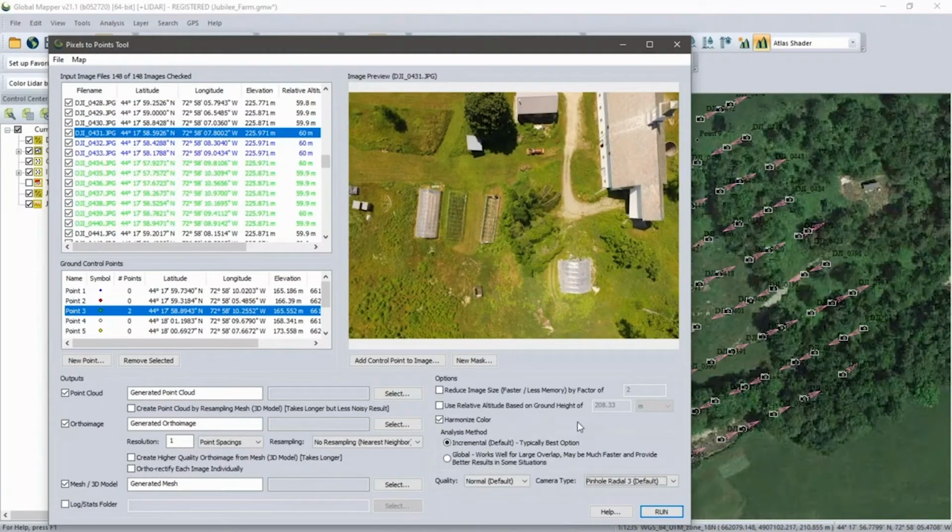Someone was asking about the coordinates, specifically where the coordinates are derived from. Is it the center of the image? To clarify, the only coordinates we have to begin with are the coordinates of the drone when the image was taken. That's what's used, and it's a simple triangulation process. If you remember back to Mackenzie's slideshow, that derives where the surface is, well, ultimately where each point is, from the knowledge of the coordinates of the camera. From that, then obviously we know what the coordinates of each point are and the geographic reference information.